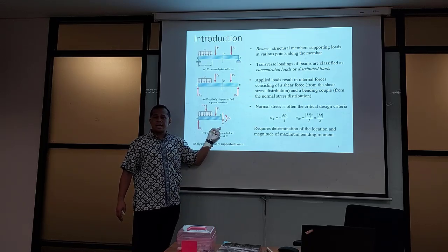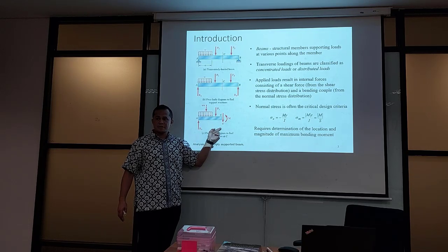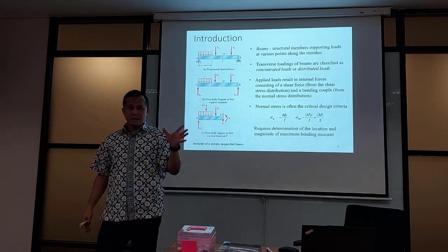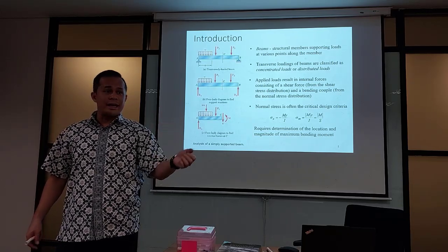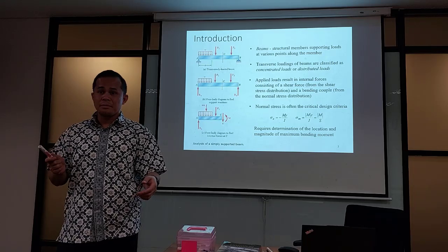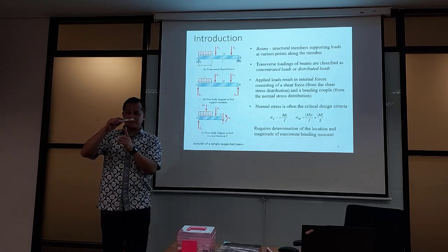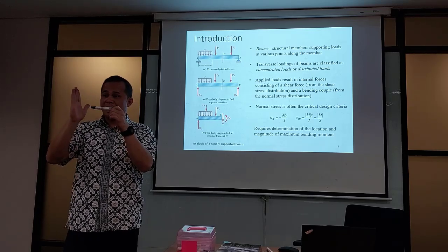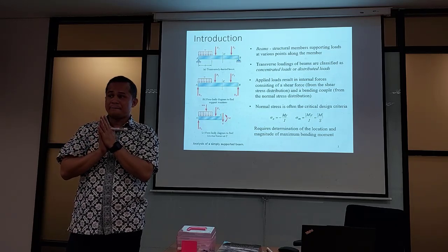The V, we call this the transverse force, or we call it the shear force. V is the shear force. The M is the bending load. Until this part, you should remember that the transverse force, when it becomes internal, becomes shear. Do you know why it becomes shear? Because it is applied perpendicular to the axis, therefore it is parallel with the surface. Thus, it creates shear. Okay?